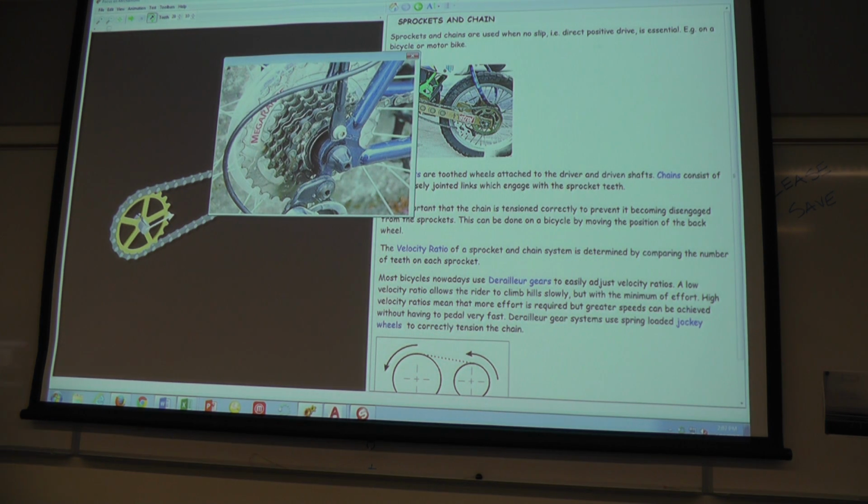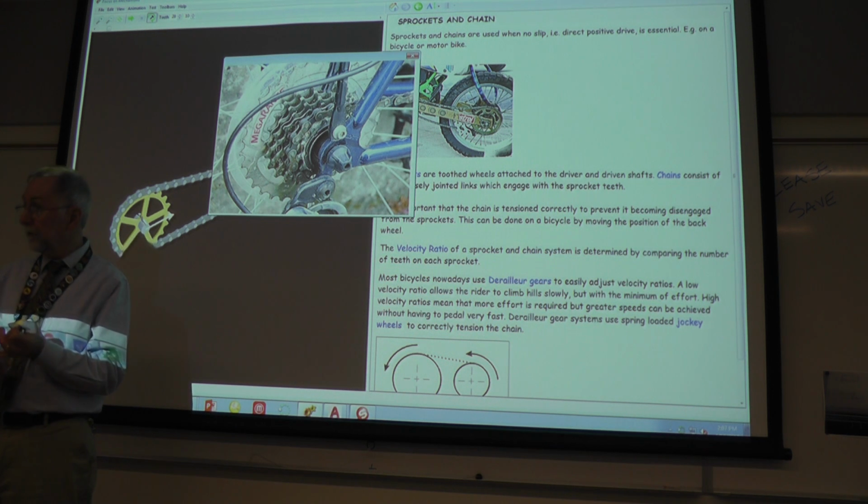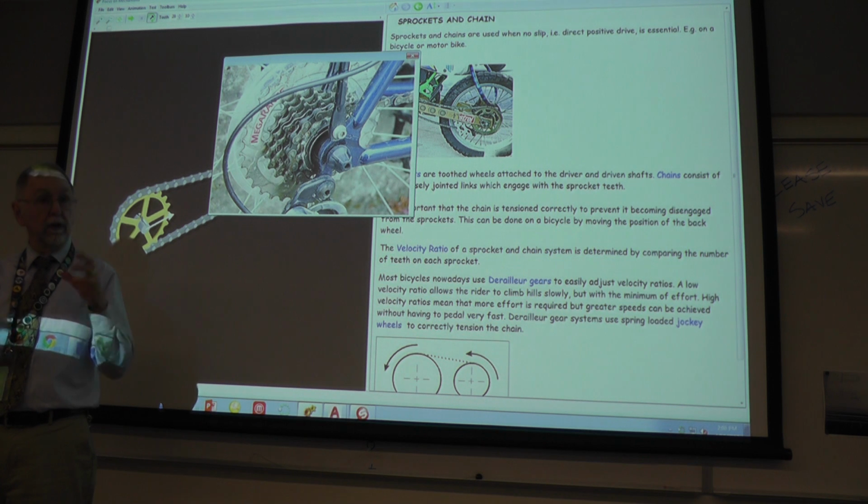Again, they're using a bicycle with the multi-gear ratio changing, quick speed changing apparatus on that. In industry, there are certain examples of that, but a lot of times it's a one-to-one driver and driven. So you will find the same sort of aspect to that as we did with V-belts. You have a driver, you have a driven. Generally speaking, the driver is the motor, and it's spinning at a higher RPM than the driven, which is some piece of equipment that has a larger sprocket to it and reduces the speed down.